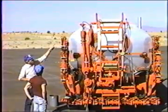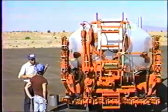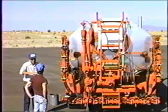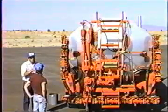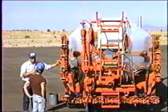When we turn the master switch on, the air is going to go to that air can. It's going to push down on the disc. In fact, on the computer truck, that always has 50 pounds of air pressure on it. So it pushes down on that disc hard enough that it would take 50 pounds of liquid pressure in the spray bar to lift the disc. 50 pounds is way higher than we ever spread at.